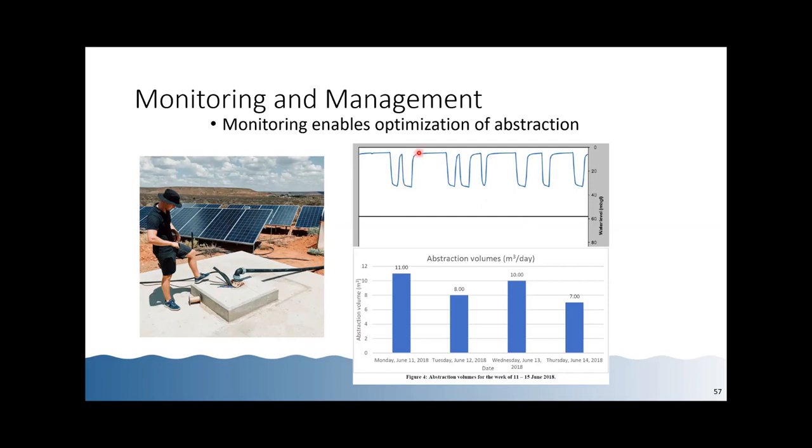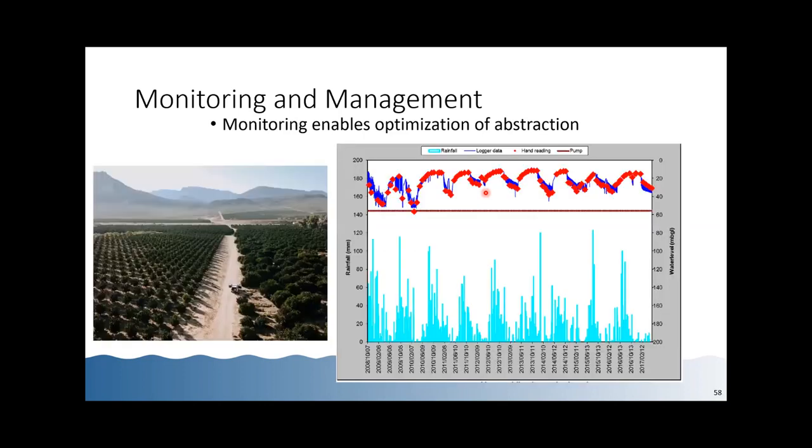By assessing this data, we could tell them two things. Firstly, they can rest easy. This borehole usage is very sustainable and is not going to fail any time soon. And secondly, they can double their abstraction from this borehole before they need to consider drilling an additional supply borehole. So real information that benefited this user and saved them the expense of having to drill a second borehole. That was 1 week of borehole data.